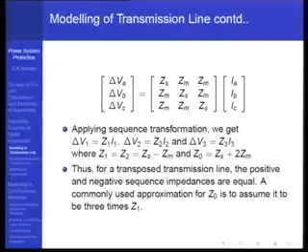But in zero sequence, the whole of the current has to go through the ground wire, or the ground, or the neutral wire, or whatever. And the ground does not really have zero resistance per se. It depends upon the terrain, and if there is a neutral conductor, how you have grounded, and so on. So it depends upon grounding practice. The point therefore is that you cannot consider ground to be an equipotential surface when you are talking of zero sequence component. But we want to consider it as an equipotential zero potential surface only.